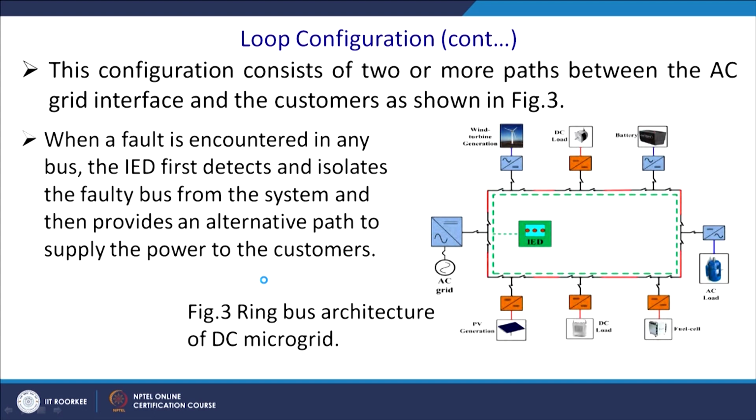So, that is your radial bus. You can see that at every point you can make and break contact. So, you can close this, or there will be islanding mode. You can close this, then power will go there. You can turn off this part of the switch. The red portion is your cable. So, again you can close this switch, power will go there, or let us say a fault has occurred here.